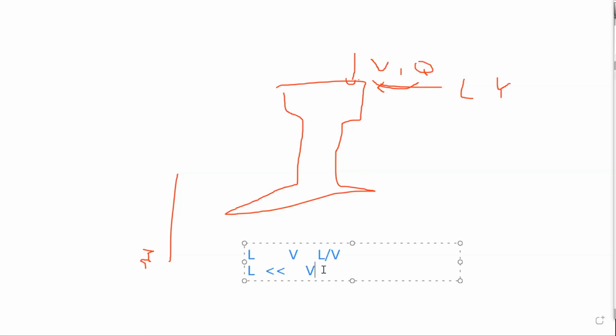So that's why with your L over V ratio, you can have a high L over V ratio with either a high L or a low V. So V sort of has to balance in between. Ideally, you want V to be your static wheel load plus or minus 50%. That would be perfect. Maybe 200, maybe 100% on the vertical side. But you never want your V to go down to less than half of its static load. And most railroads hit your safety standard at around 25%.